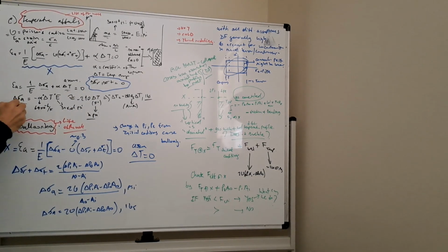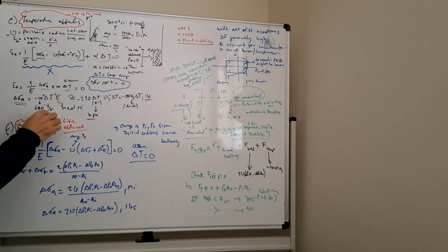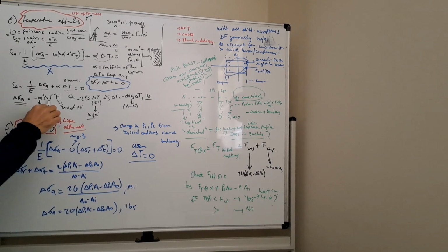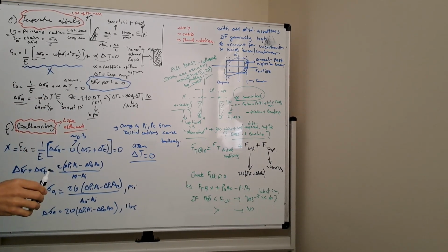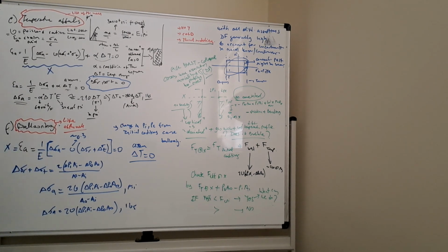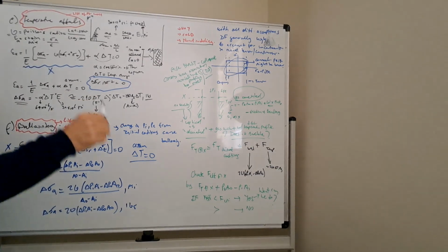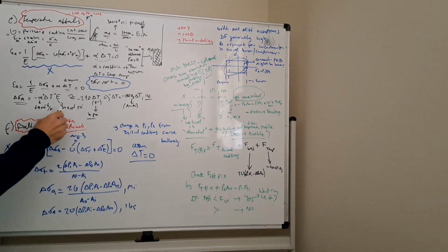So the change in the axial stress will simply be equal to the coefficient of thermal expansion times delta T, change in the temperature from reference temperature, which in our case is the initial conditions, the post-cemented profile, and then we multiply that with the Young's modulus.